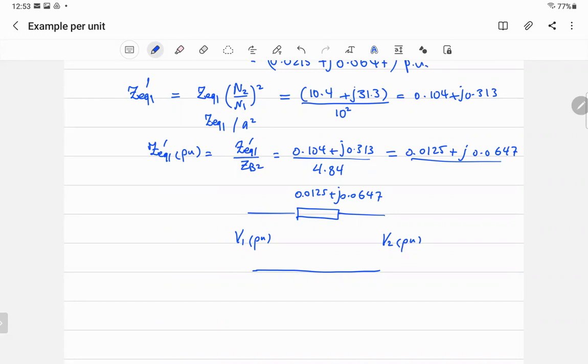Power loss, something lost. And copper, it has a historical background, but any power loss in any resistance of any wire, they call it copper loss, because the wire is made of copper, it has a resistance. Before they used to call it copper loss, and until now, they still call it copper loss. What it means is I square R. It's the loss in any resistance of the wire.